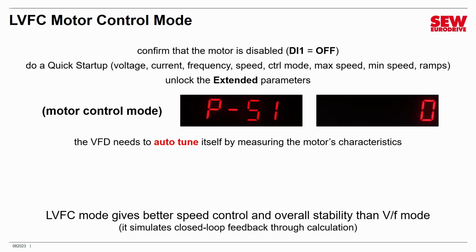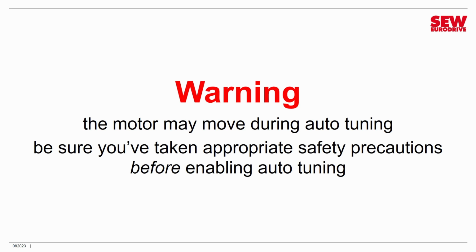Now, the way you trigger this is relatively simple. You just have to set a parameter, but before we talk about that, I want to give you a warning. The motor may move during auto-tuning. So be sure you've taken appropriate safety precautions before you enable auto-tuning. In other words, the motor must be able to run, and it must be able to run safely. It may or may not move, so just consider the possibility that it could.